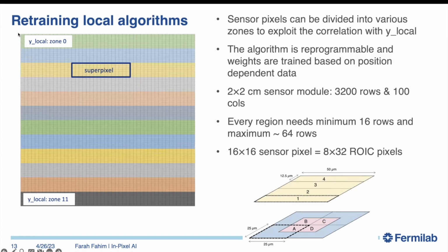So we are expecting something like 400 times 2, so 800 pixels along the y-axis, or 1,600 pixels along the y-axis and about 400 pixels along the x-axis. That's because our pixels are not square, they are rectangular. So the 12.5 micron dimension is along the Y, and the 50 micron dimension is along the X. So if you do this, you can basically divide this up into several different regions.